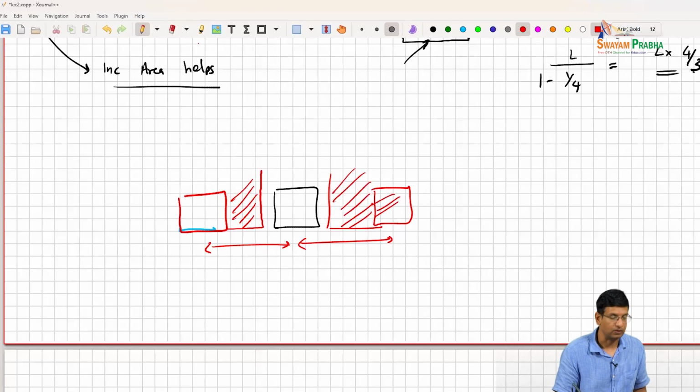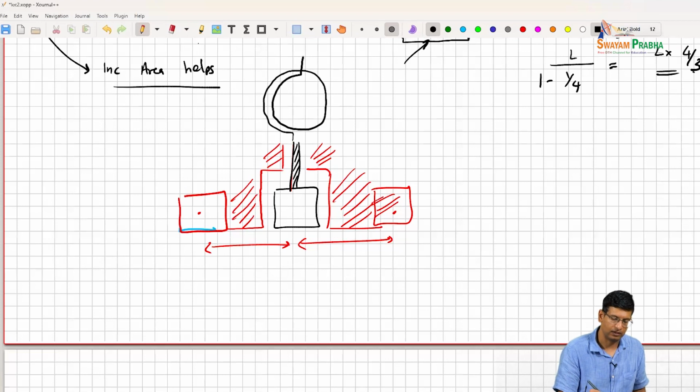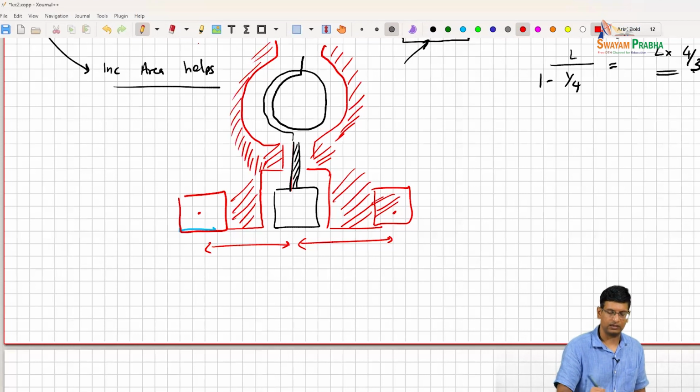So that's the first step that you do, where you are making contact with the pad to this point is a very small resistance, and then over here, let's say that you have this and you have this, you have your signal trace coming out, right? And then let's say that you have an inductor. I'll just draw a 1.5 turn inductor going out, right? And what you do is around it, you are basically modeling the ground. You are placing a ground, right? So now the discontinuity that is happening is this particular part here, right?